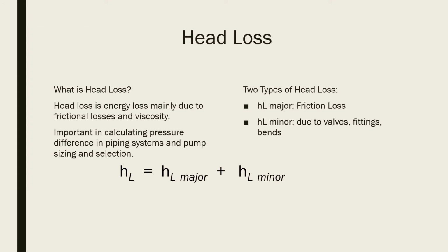So first off, what is head loss? Head loss is essentially the energy loss due to frictional losses and viscosity. This is really important in fluid mechanics to calculate pressure difference in piping systems and also pump sizing and selection, such as when calculating the NPSHA.